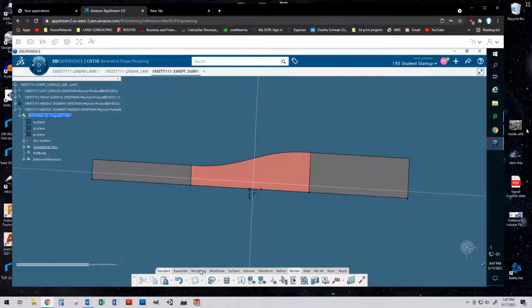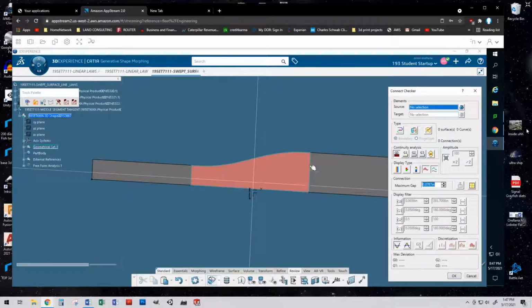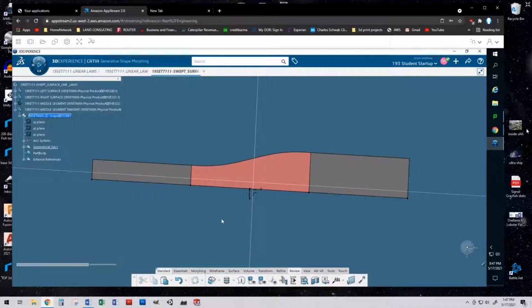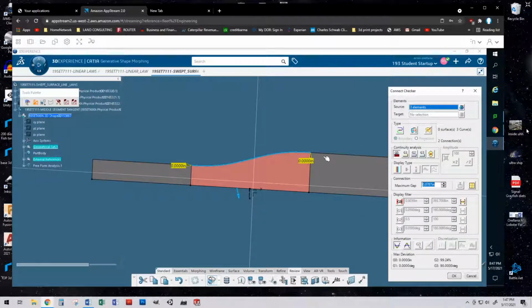Oh, look at you. Gonna get fancy and check the tops, check the surfaces. You want to cancel that, and let's try this. Use your control button and grab all the top 3 edges, and then hit that function. And what I'm looking for is my G1, so click on G1, and what's that tell me?